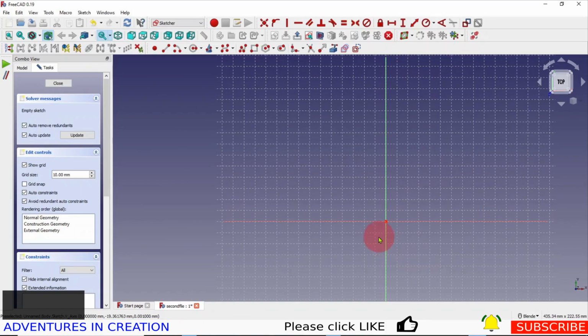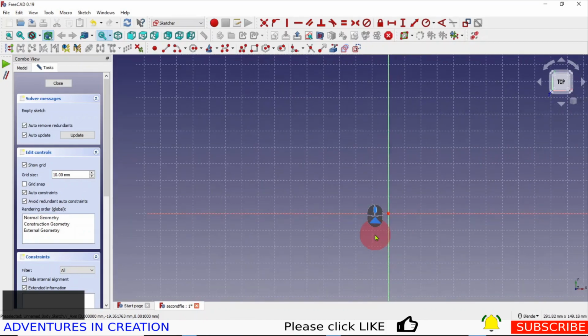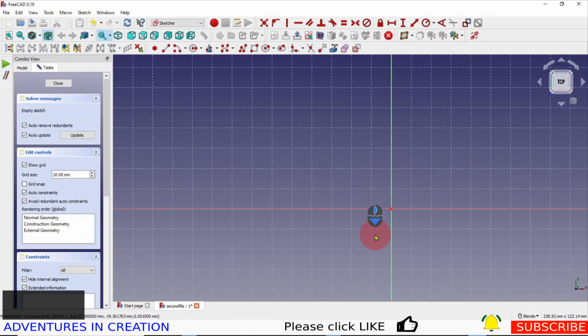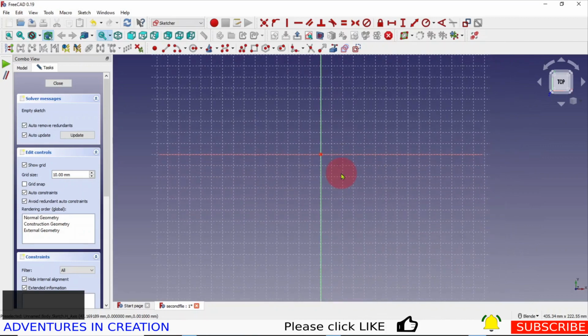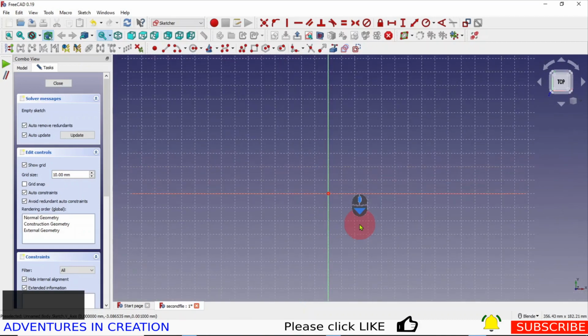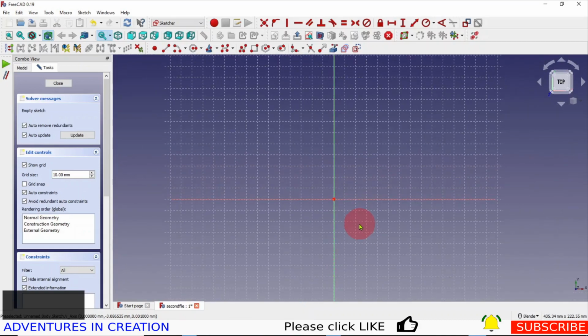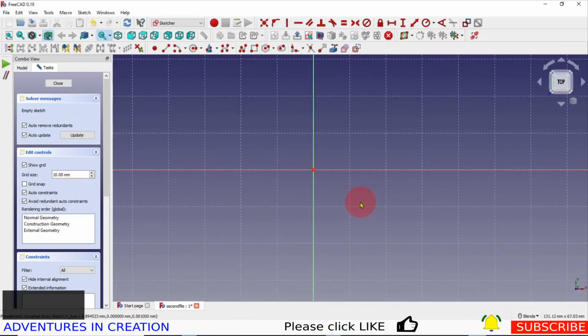Now, if you want to zoom in, zoom out, it's just the scroll wheel, the middle wheel. I'm just scrolling that up and scrolling it down. If I want to move it over, because I want this center point to be up here somewhere, I press Shift, click that center, and it allows me to move it. It's a good idea to get used to that, because sometimes your drawing is over here in the corner, and you actually want it in the middle, and you want to be able to shift around in it. So zoom out with the scroll wheel, hold down Shift, click the scroll wheel, move it around to where you want it, and then zoom in.